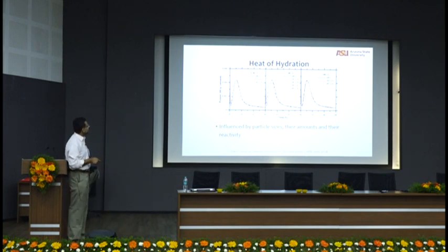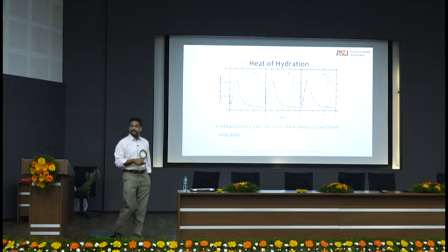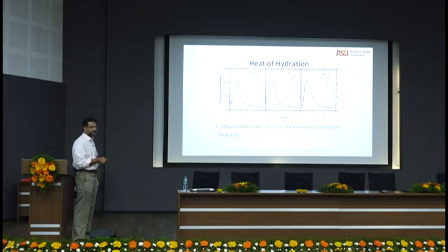Look at all these cases. When I get to a 15 micron limestone, what is the importance of 15 micron? Roughly the same size as cement. What's happening to it? Whether I put in 10%, 20%, is there any change in the total heat of hydration? Why? This is what I call cheating the system. This is how you cheated the system by putting in limestone.